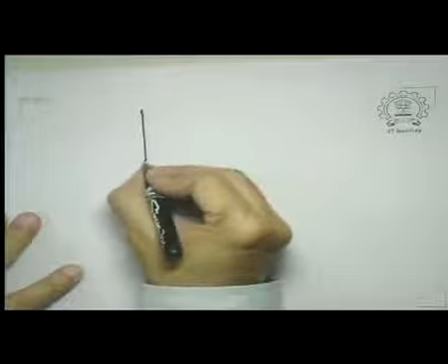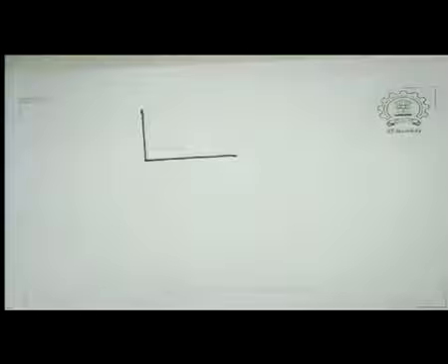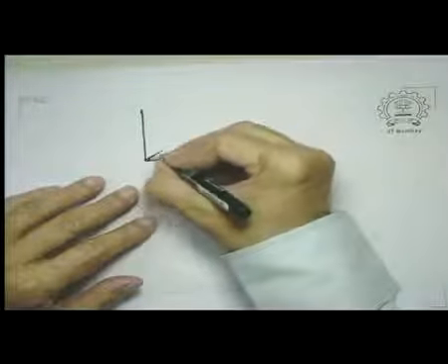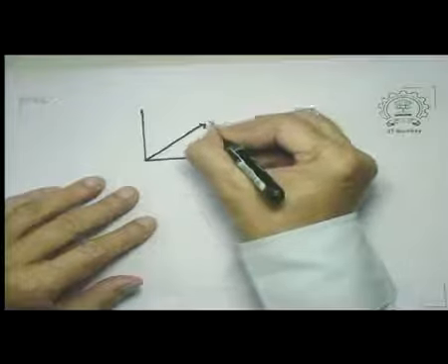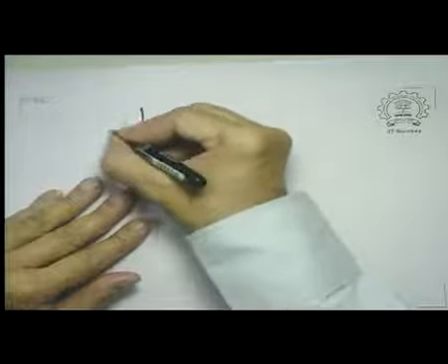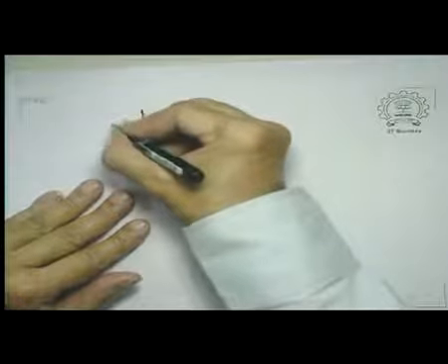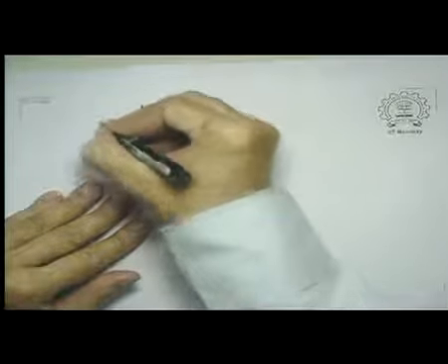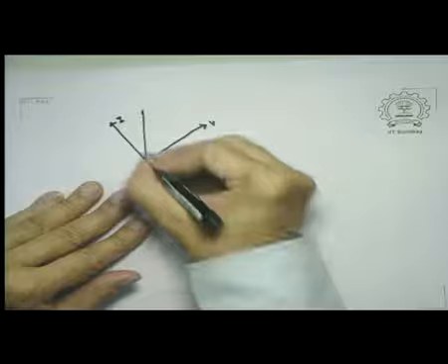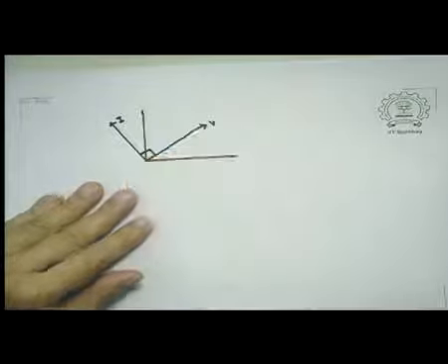If you look at the phasor, then what you find is that because the current leads by pi by 2, they would be on two consecutive quadrants of the xy plane. So, for example, let us take this as your V, then since the current is leading by 90 degrees, this should be your current, and so this angle is 90 degrees.